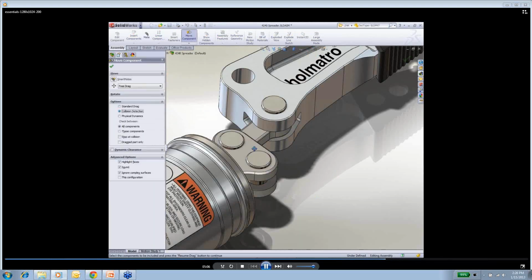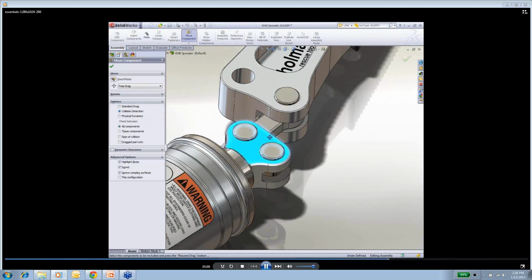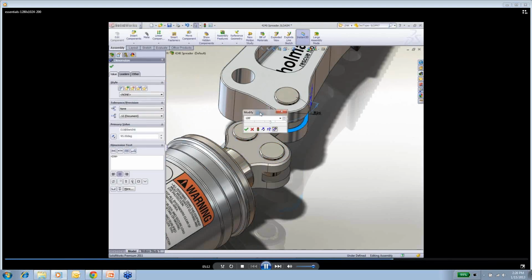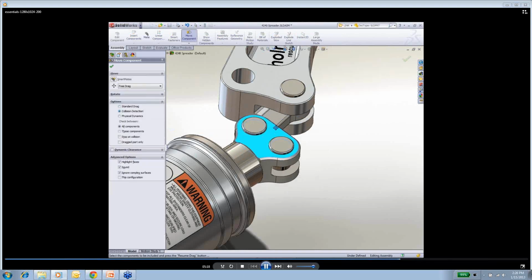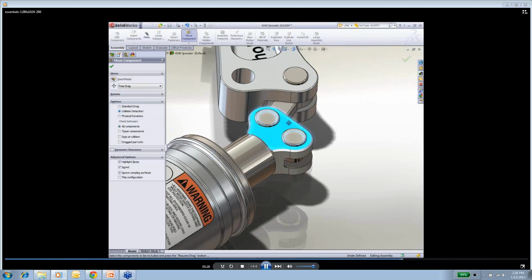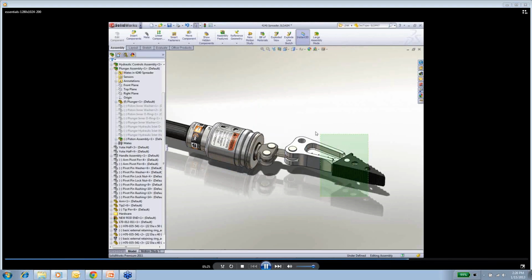Now, another powerful tool in SolidWorks is collision detection. One of the main reasons that people go to 3D is to make parts that don't interfere and won't require rework when you go to manufacturing. So you can check for that. And here I've modified that part. I've made that slot deeper. Now when I check, I don't have any interference.